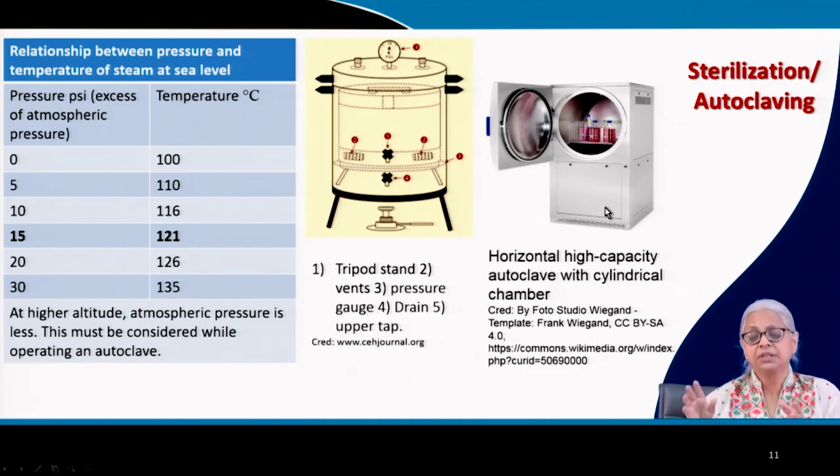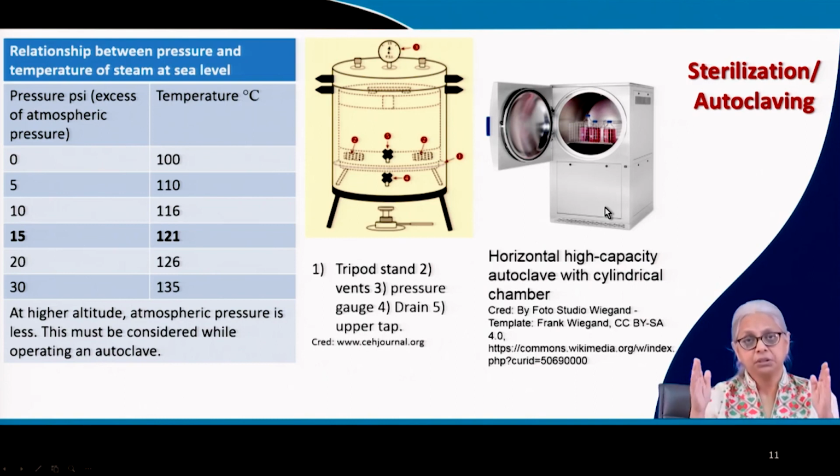Now, a very important point in autoclaving is that the entire cycle, in practical terms, from the point of closing the door to the point when it is safe to reopen the door can be anywhere from 1.5 hours to 3 hours or so. But the actual autoclaving time is actually 15 minutes because it takes a fair amount of time for the steam to build up. You have to maintain the steam and pressure for 15 minutes to ensure that you get complete sterilization of the equipment, both the dry goods and the wet goods.